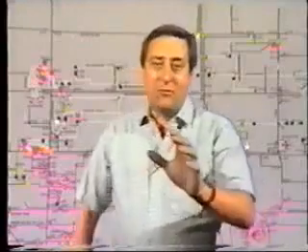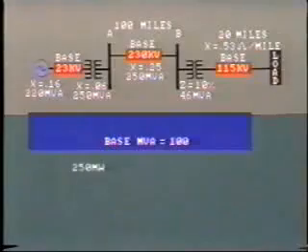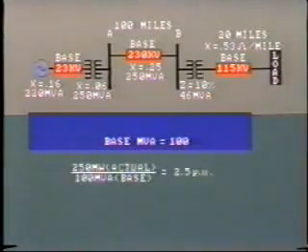The value for base voltamperes is chosen arbitrarily, and it must be used consistently throughout all of the calculations. Unlike the voltage base, there is only one base voltamperes to be used throughout the whole system. This is very often chosen to be 100 MVA. 100 MVA is a nominal magnitude for most power systems, and a number easy to work with. This base is used for both megawatts and megavars. For example, 250 MW would be 250 MW actual power divided by 100 MVA base power, or 2.5 per unit.